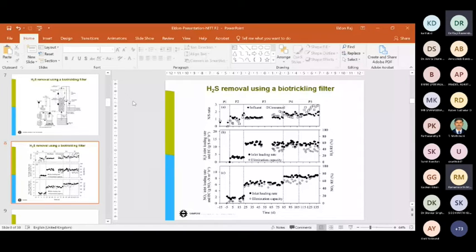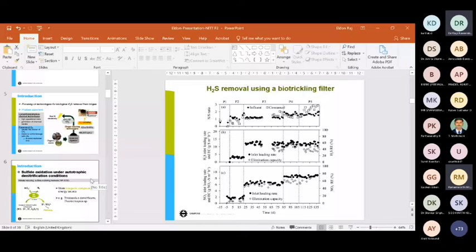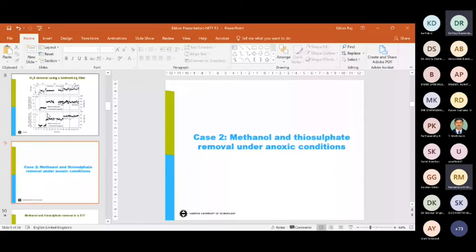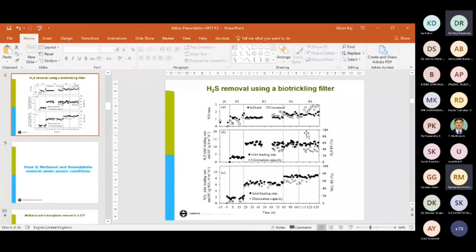Okay, so under such conditions, you may have a deficit in the removal efficiency. But interestingly, what we also observed in this treatment was you will be able to close the mass balance, because we measured the nitrate, nitrogen, and the ammonia and all the other species that were present. And especially for sulfur, we monitored the sulfide in the liquid phase, and we measured H2S in the gas phase.